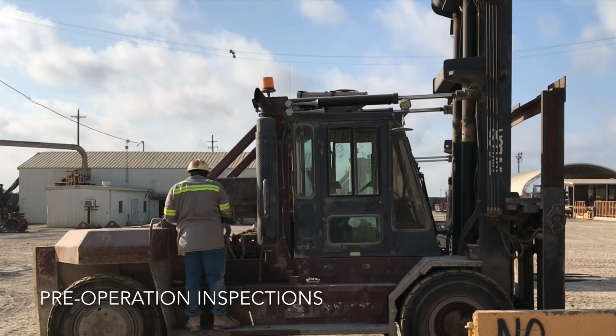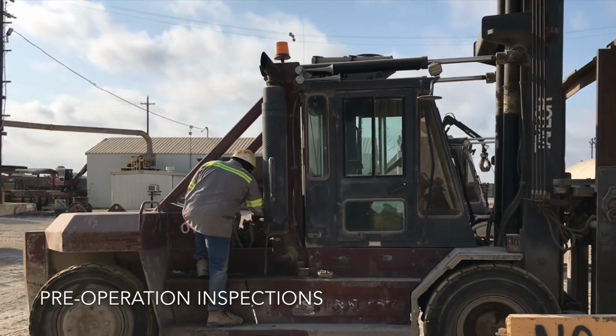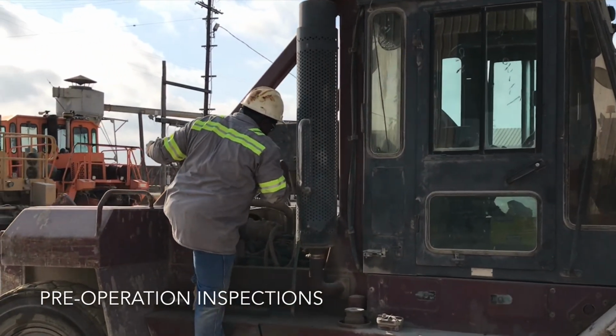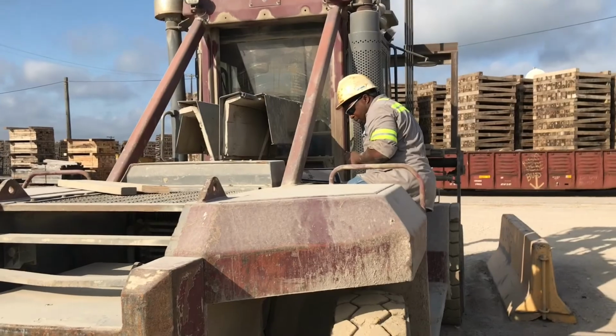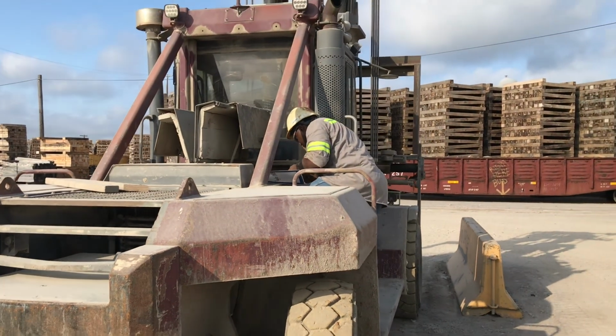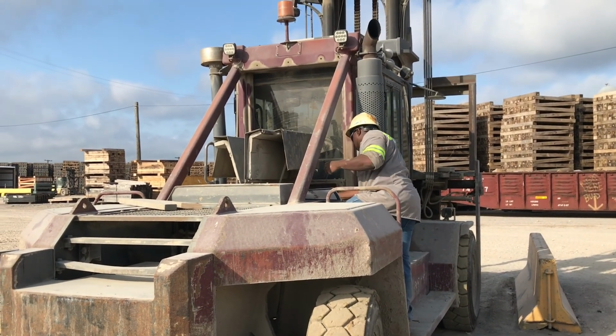Mobile equipment pre-operation inspections should always be completed before operating equipment. These inspections not only help determine if equipment is in operable condition, but you will also be able to tell if the equipment has any leaks. If equipment is found to be leaking, document the leak in the inspection and have maintenance personnel evaluate the equipment.